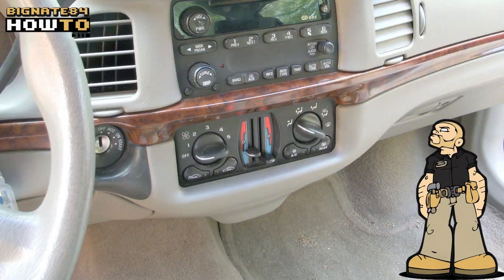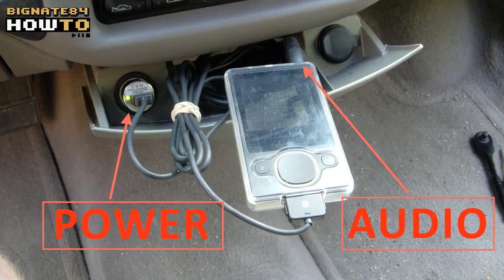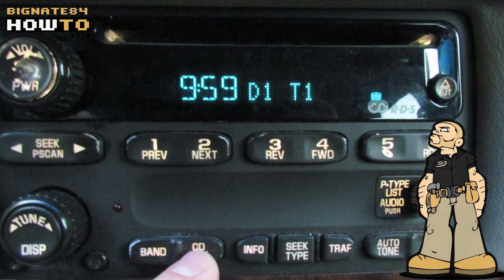In this video, I will show you how to turn the ashtray of your car into an auxiliary audio input, let's say for an iPod, Zune, or any other type of MP3 player you may have. I will be using the factory radio of a 2002 GM vehicle that has no audio slave unit. Keep in mind, audio slave unit is just a technical term for external CD player or any other type of external device that is controlled by your car's radio.